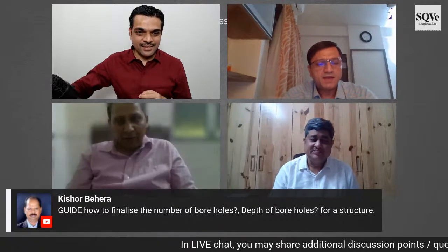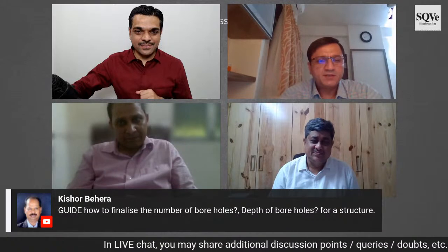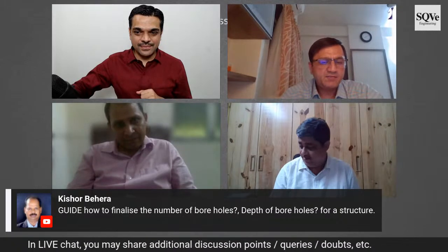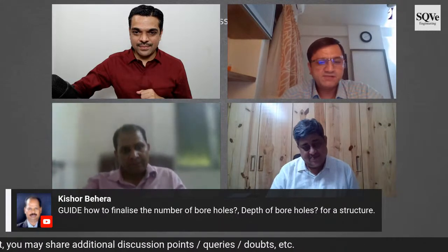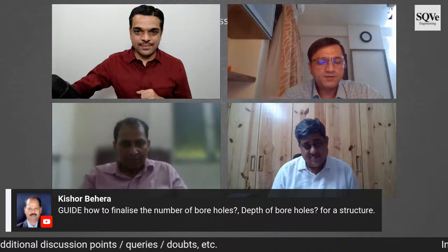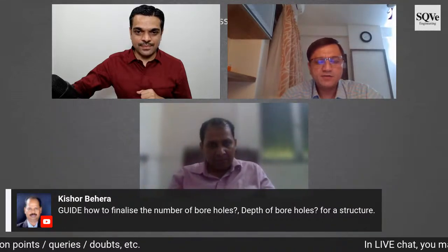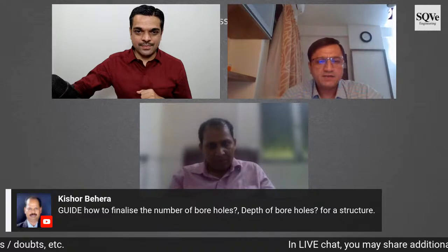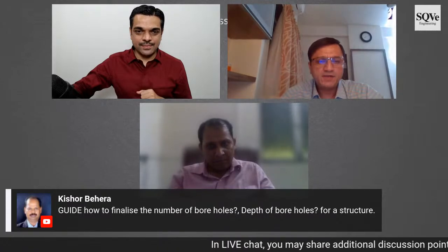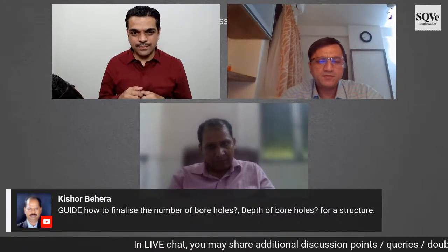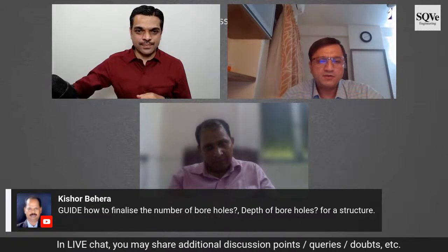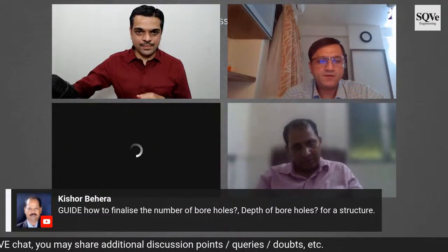So even, let's say, for a preliminary investigation. Dr. Shukla, yeah, what we are looking at. I think the preliminary guideline can be tentatively based on the width of your foundation. So at least you need to investigate 2 times or 2.5 times the width of your raft or foundations below the deepest level of your foundation.